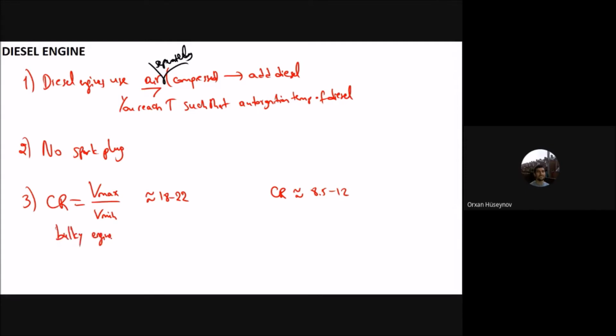They are very large. But for petrol engines, the compression ratio is small, and therefore the engine itself is small, because volume means the space that it holds, so petrol engines are not as large as diesel engines. But we said in our last lecture that this high compression ratio gives high torque to the diesel engines. That high torque is used for heavy trucks. For example, the bus or the train, all the heavy vehicles use diesel engines. These are the main differences, but the compression part is the most important.